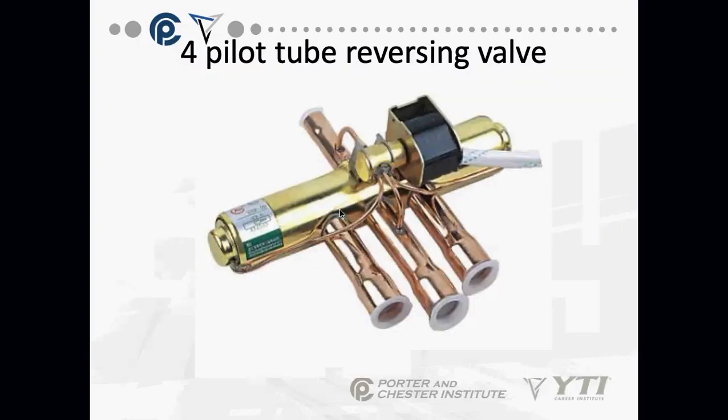Reversing valve, again, when you're looking at it, this is a brand new one. You have a solenoid coil that is mounted on the pilot valve assembly, which I'll talk more about tomorrow. The solenoid coil is what's connected back to my thermostat. There's an O terminal on your thermostat. When O is energized, we're in cooling mode. When the O is not energized, it's in heating mode. And this is what you get to braze in if you ever have to replace one of these.